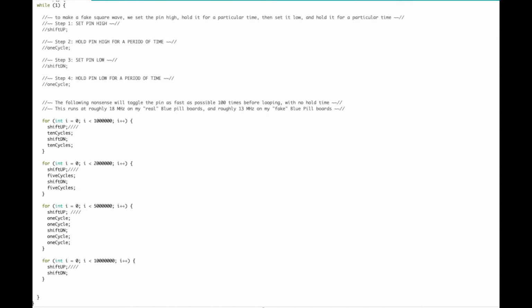So instead of a sweep, I'm going to use a stepped signal, and I just took my ugly blue pill square wave generator, the Arduino sketch, and cycled through from like 2 megahertz to 5 megahertz to 10 megahertz to 18-ish megahertz, and then fed it into one channel of the front end of a 100 megahertz oscilloscope that also has 20 megahertz bandwidth limiting, and fiddled with the trigger until I got them all on the screen at the same time.